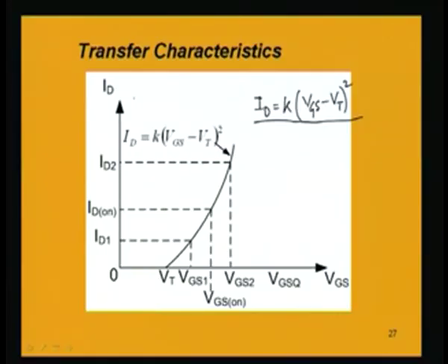That means, on the same axis as we have drawn right now between ID and VGS, we will be taking the same axis, ID in milliampere and VGS in volt. Start with the threshold voltage, that is the voltage between gate to source till when the drain current is 0. So, this is the point, say. One point is on this VGS axis, which is the threshold voltage.